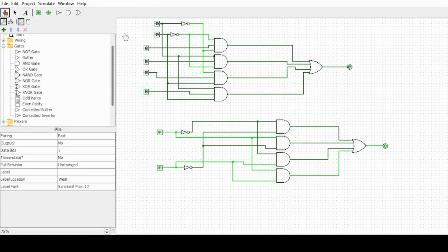So let's say these are the data sources, and we label them as input 1, which is 00, input 2, which is 01, input 3, which is 10, and input 4, which is 11. If we select data source 00 and turn this one on, you see it didn't turn on because this is 01. But this input, it is 00. So 00 is allowed to pass through because the selector is at 00. Meaning we've told the system that only 00 should pass through. So if we select this, it won't go.